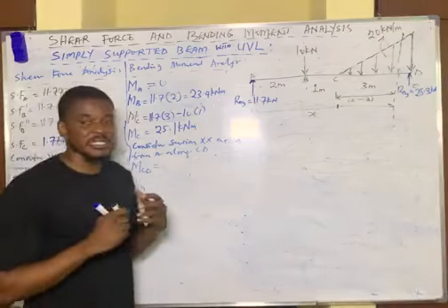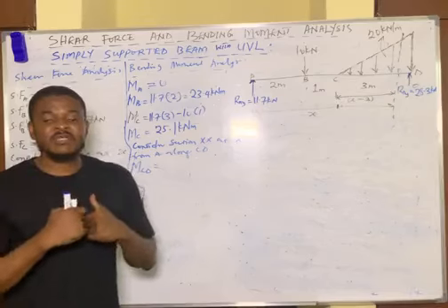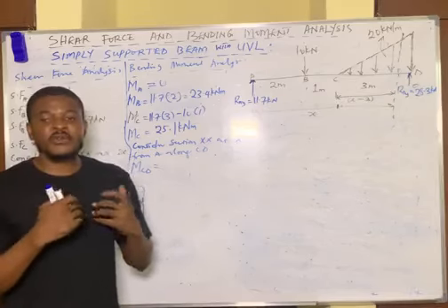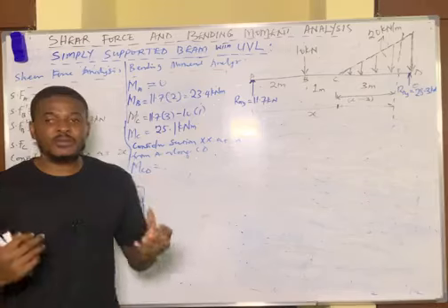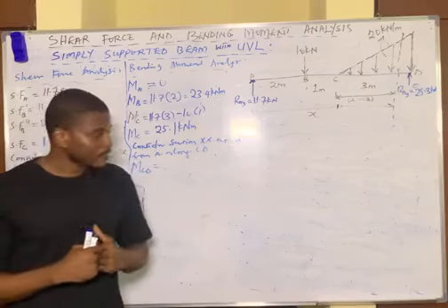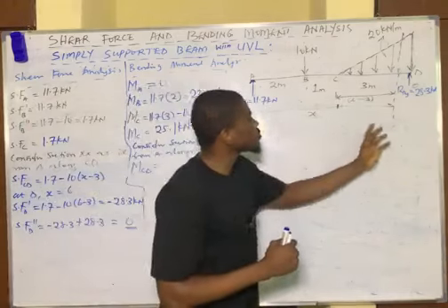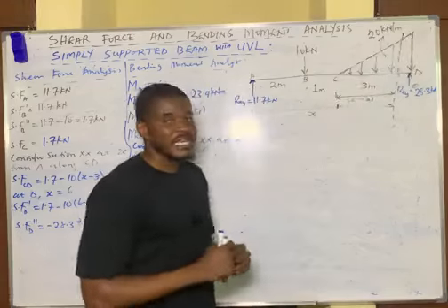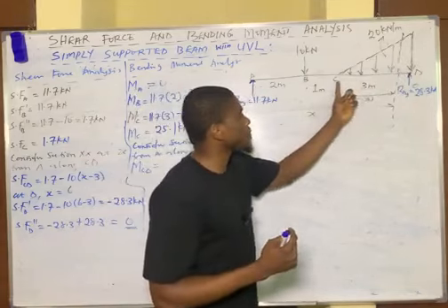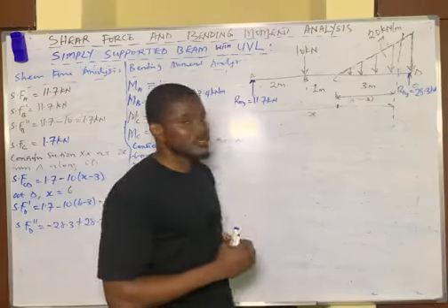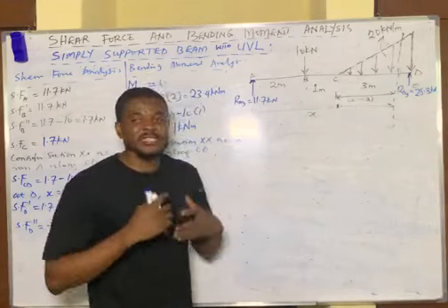Now, this is what happens. This helps us to now form the bending moment equation. It is the value of X from this equation that tells us the point of contraflexion. When you equate the bending moment equation to 0, the value of X obtained is called the point of contraflexion. Now, we are simply saying from point A to somewhere along CD is X. And we have established that the length of the UVL about the point of section from point C to the point of section is X minus 3. We have established this. Now, remember, moment is force times distance.